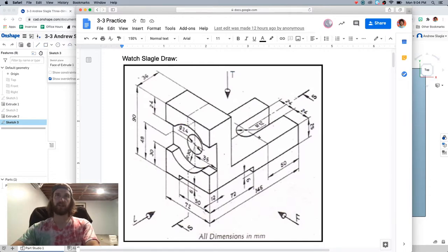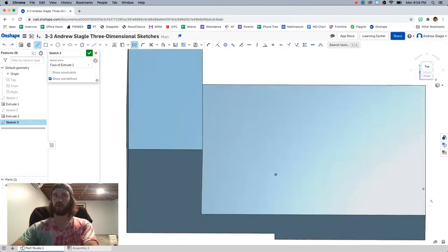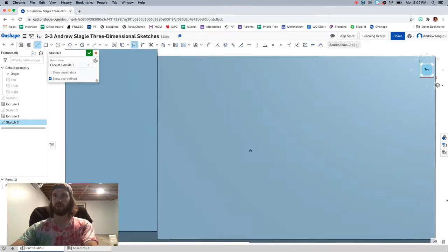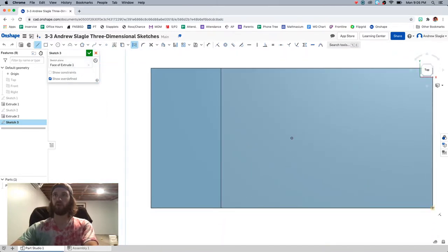So I'm going to draw my rectangle, 50 by 24, and I'm going to come in and draw a circle that has a radius 12 that matches up. So it'll have diameter 24, which means it'll span perfectly across this rectangle. Alright, so here we go. Let's do that. 24, I'm going to use a construction line because I'm measuring out to the spot. Make sure I'm in the right position. Yep. Draw that out. Come out this way. 24.